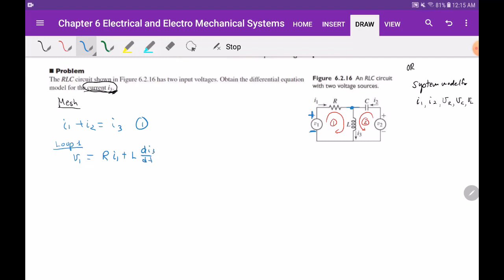What you actually want to do is not stay in the time domain. So you take a Laplace transform of the whole circuit, and you replace everything with impedance. Whenever you see C, you have 1 over CS.